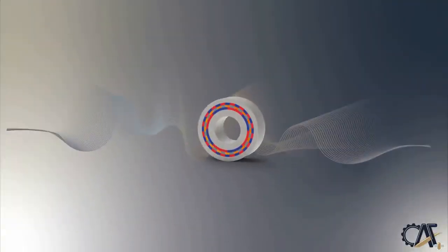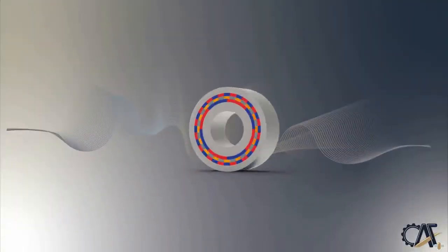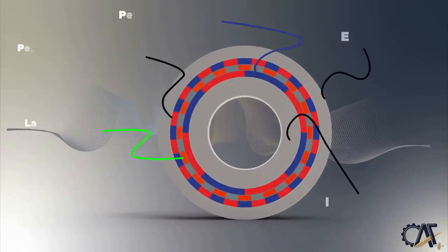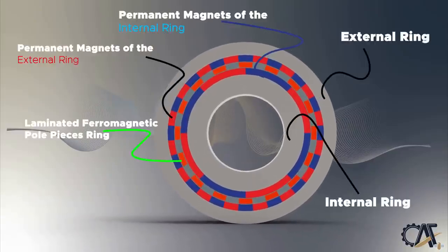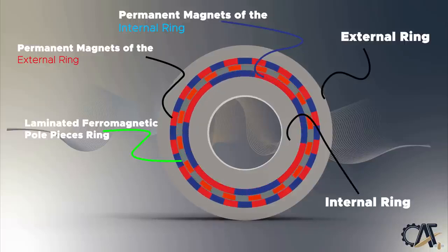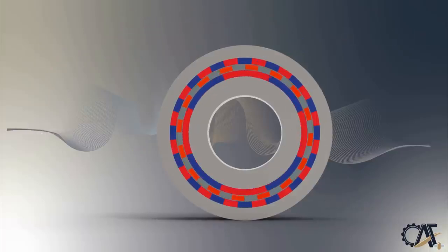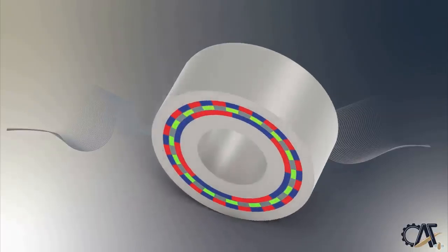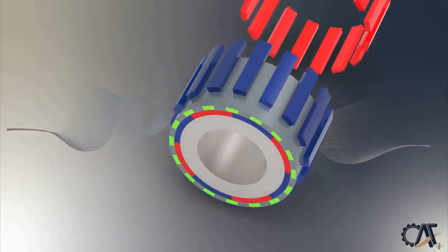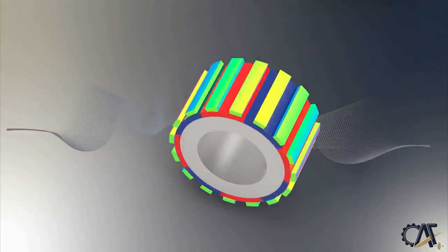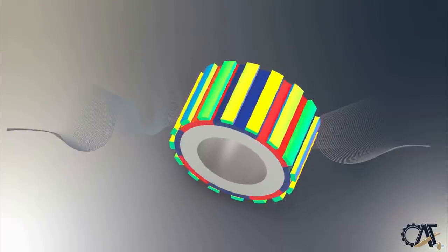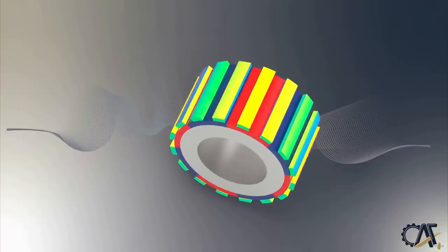A magnetic gear is similar to a mechanical gear in function but uses magnets instead of teeth. Here you can see the main components of a magnetic gear. The gears don't touch at all, they only interact magnetically, which makes them unique. The gear ratio is determined by the number of magnets used in each rotor. Magnetic gears are relatively new in the industry. In recent years, the magnetic geared motor has emerged as an interest in electric vehicles and electric bikes.